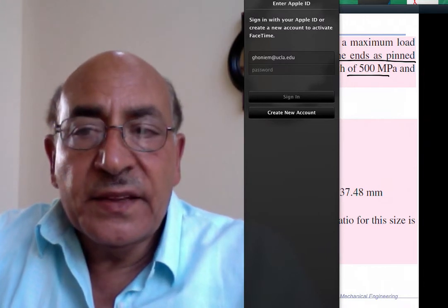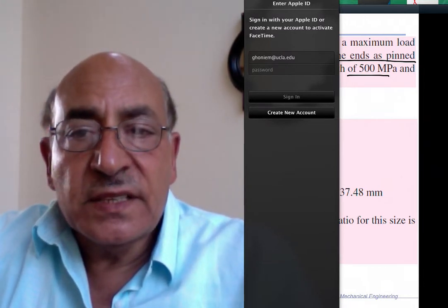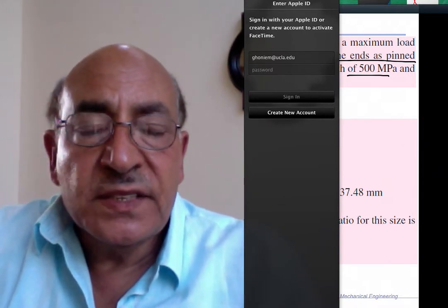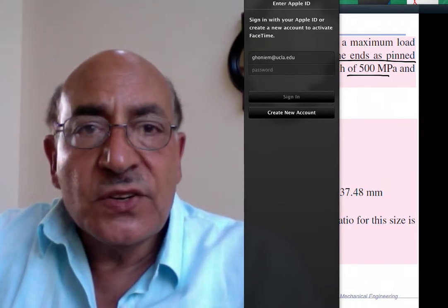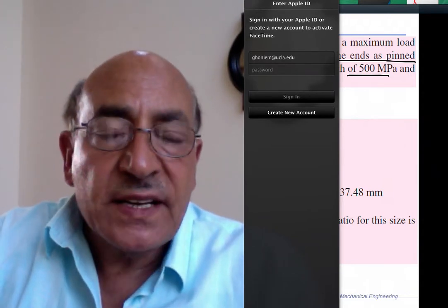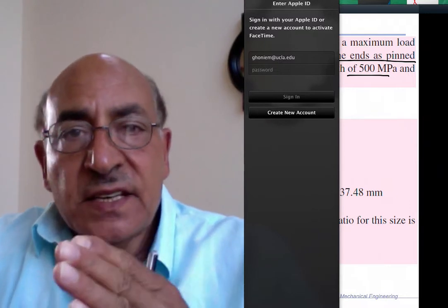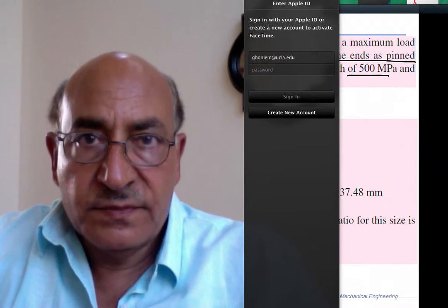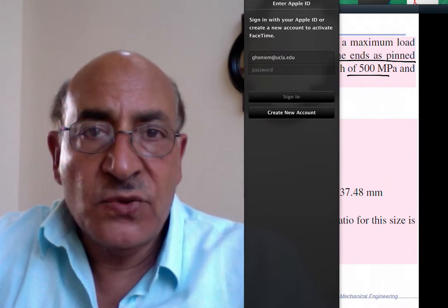And then we just go straightforward first to determine the diameter using Euler formula, and then hope for the best. After we find the diameter we have to check the slenderness ratio: is it greater than L over K sub 1 or less?